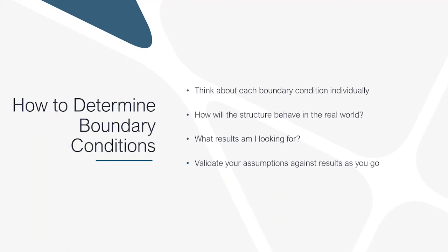Think about what information you want out of your model and how the boundary conditions might affect that information. Are you just looking for deflections, for example, or are you looking for member force demands so that you can design that member? A good example of this would be, again, going with a simple beam example. If you have vertical supports for your simple beam and you're trying to decide if that support should be vertically rigid or if you should model it as a vertical spring. Well, if you're just looking for bending moment and shear in the beam, does it matter if it's fixed or a spring? Is that even going to impact the bending moment and shear demands? Not really. But if I want to understand the total displacement of the system, particularly at the supports, are you going to get accurate results if you model them as rigid? Definitely not. So you just need to take it as far as necessary in order to get accurate results for the things you actually care about.